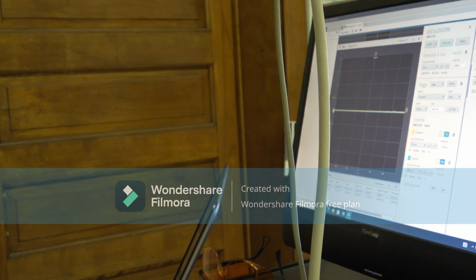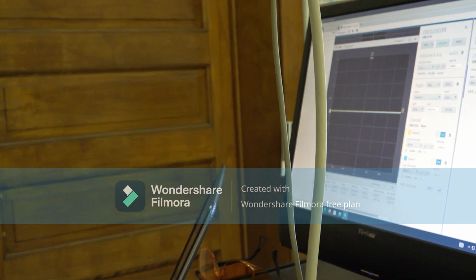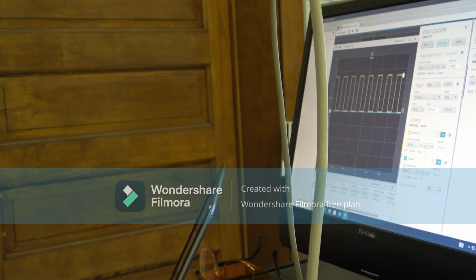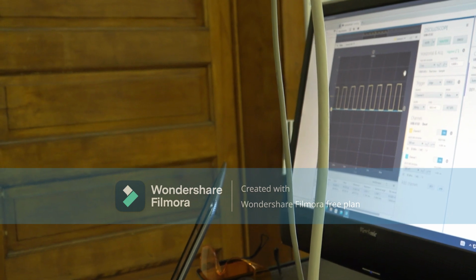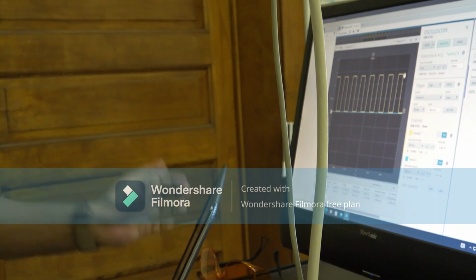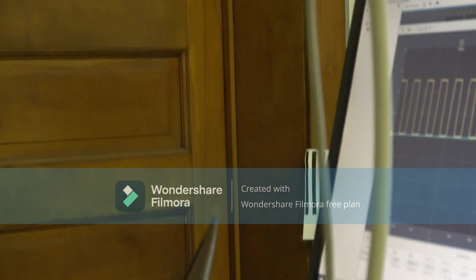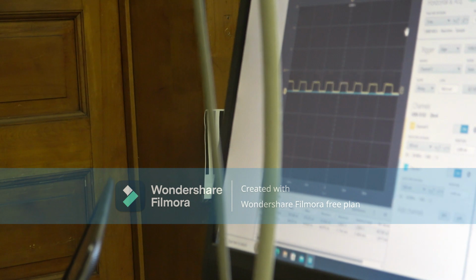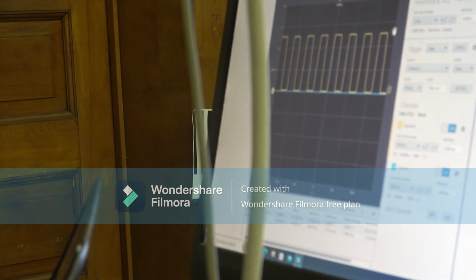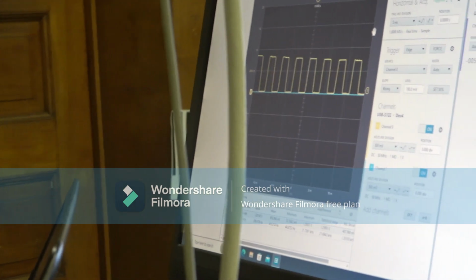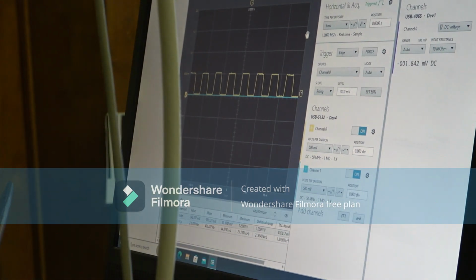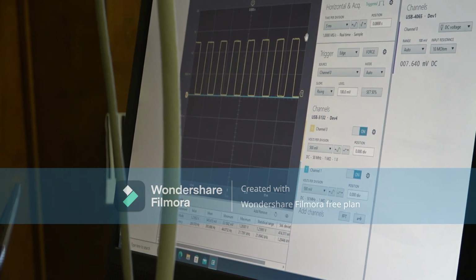Now we'll develop a calibration curve for the photodiode, to relate the photodiode input voltage to the power of incident light. This can be done by placing the neutral density filter wheel and chopper wheel between the beam splitter and the photodiode, with measurements taken for each ND filter. These measurements combined with the previous calibration are used to calculate the power incident on the photodiode. A plot is then made to visualize the relationship between the photodiode voltage and the incident light's power.